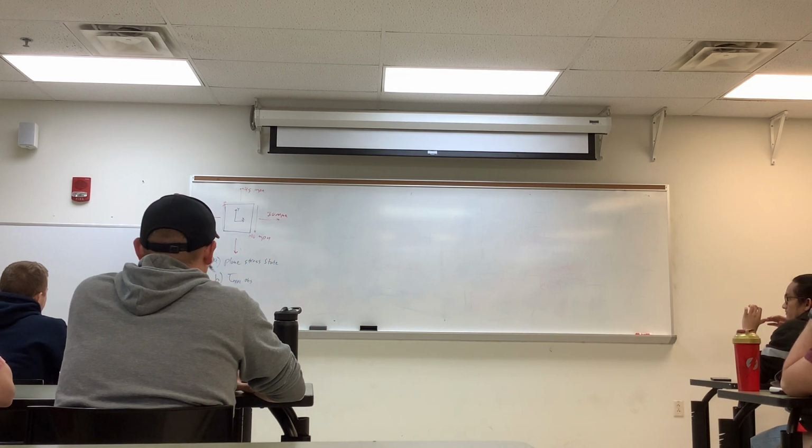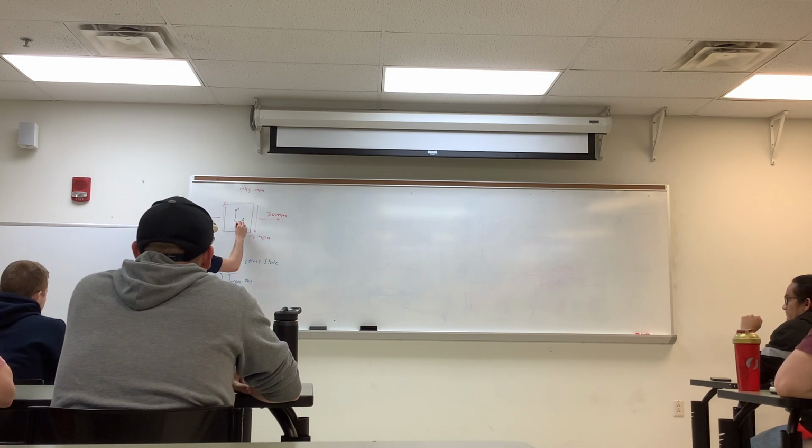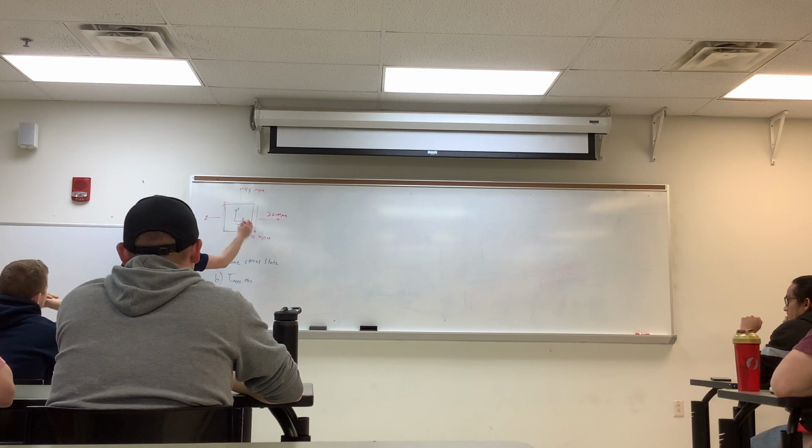The big one, or at least how I've always interpreted it, is I will look at predominantly this x-axis when I'm trying to figure out if the shear is positive or negative, and then the corresponding one about the top. If they're going in the same direction, it will be positive, opposing each other negative. That's how at least I've always interpreted it. If you guys have another method of how to do it, by all means go for it.